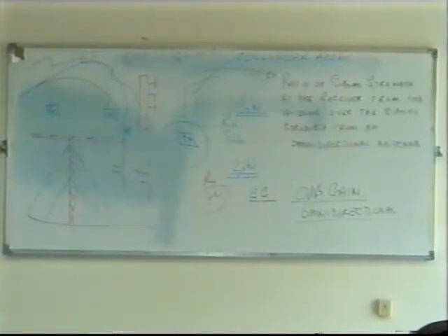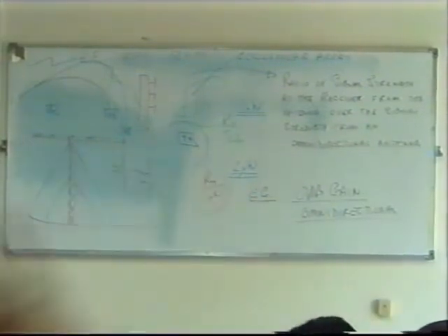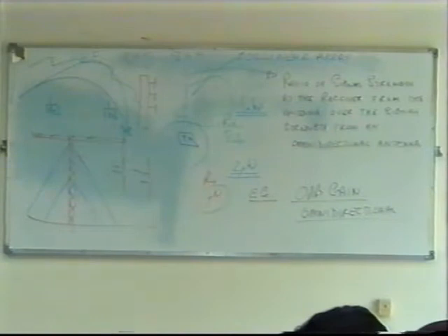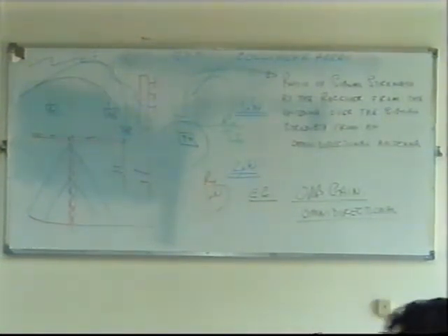Again, a Yagi uses one dipole and what they call directors. They're passive. They're only there to direct. That's right, they're not connected. Exactly. The passive elements are just there to receive the signal and retransmit it like a little reflector. You can get passive elements at the back of the antenna as well, at the back of the dipole, which are reflectors. Whether they're directors or reflectors depends on their distance away from the dipole and the wavelength of the frequencies you're using. That's what affects it. But yes, a Yagi uses a single dipole and a number of directors, maybe a reflector.